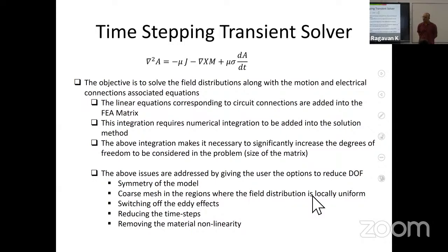There is no written rule. The rule is like you set a tolerance and keep on reducing till you reach that tolerance. Trial and error. Yes. Multiple iterations will be required. Yes. I mean, the trial and error can be made systematic by writing a code that interacts with the solver. Just run that code and make that code stop whenever you reach the estimated resistance value within that tolerance. Right?